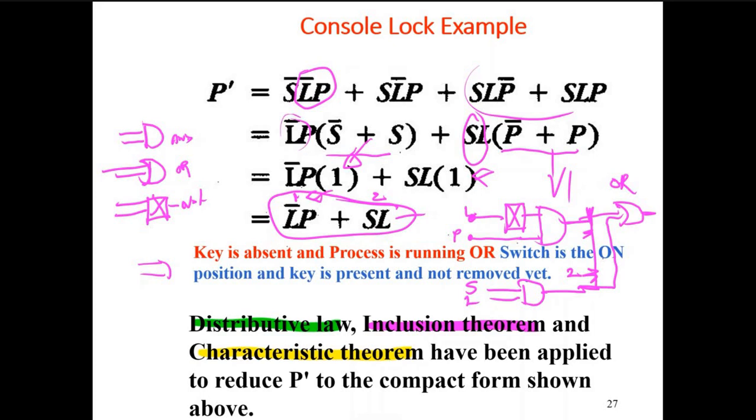But you can imagine if these equations become complicated, this goes to more complexity. You have got to do more things. This is where a PLC would give you more flexibility. If the process changes, I'm going to add a few more. Or I'm going to move my controller to controlling a different process altogether. Easy. Just take the PLC, rework your program, download, and you're done. So keep that in mind, that's how we can move.